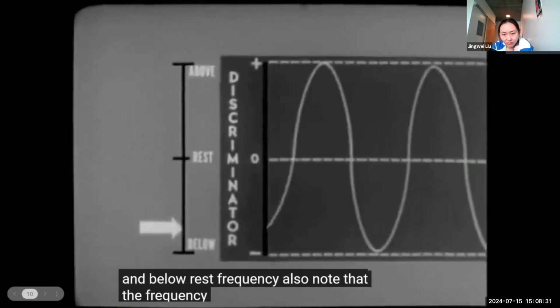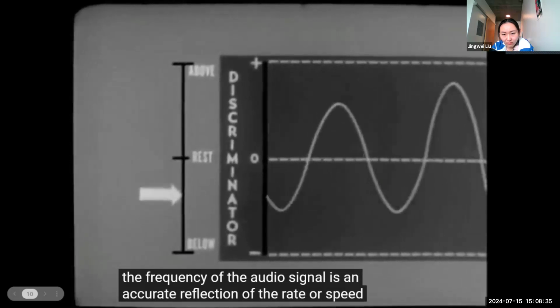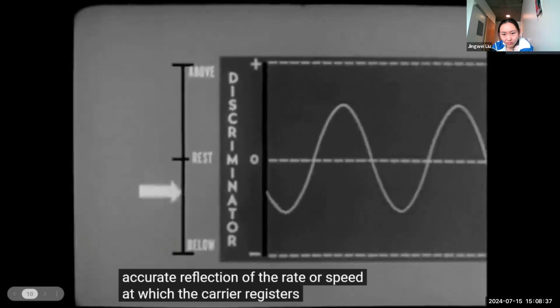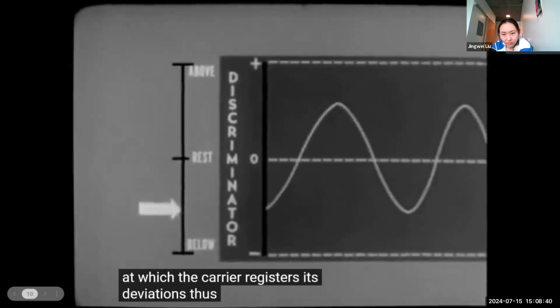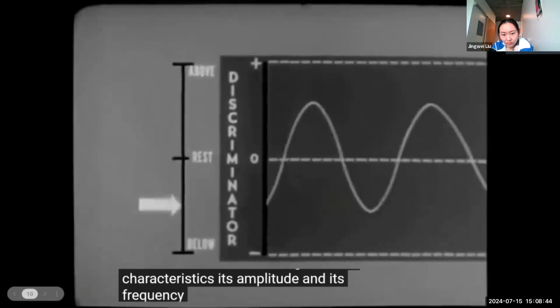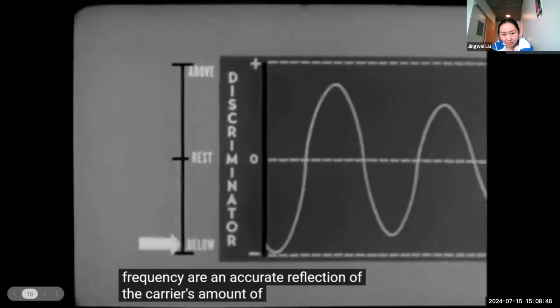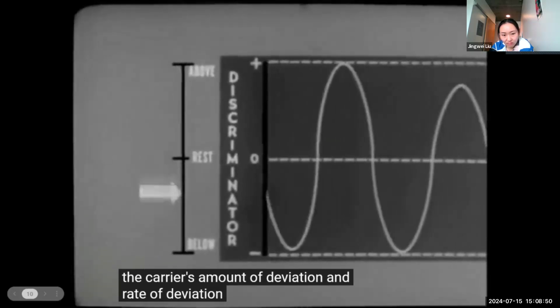Also note that the frequency of the audio signal is an accurate reflection of the rate or speed at which the carrier registers its deviations. Thus, the audio signal's two characteristics, its amplitude and its frequency, are an accurate reflection of the carrier's amount of deviation and rate of deviation.